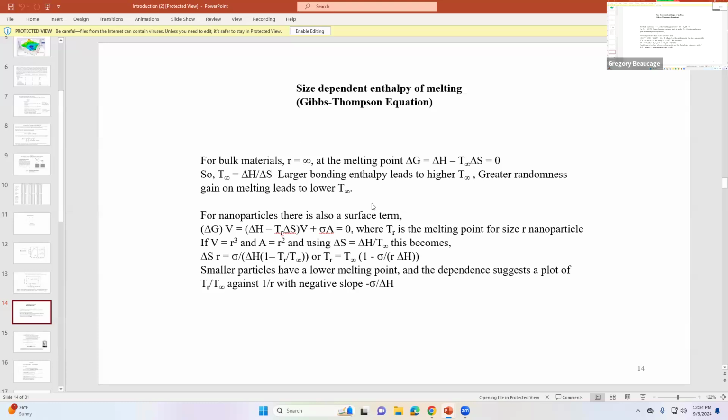So then you take this free energy expression and you add in a term for the surface area of the particle. If the particle is spherical, the area goes like r squared, and the volume goes like r cubed. You simplify a little bit, but it'll be a geometric factor depending on the shape of the crystal. So these are volumetric terms. You take the volumetric enthalpy and volumetric entropy times volume, and then the surface energy times the area. Then you swap out r cubed for volume, r squared for area.